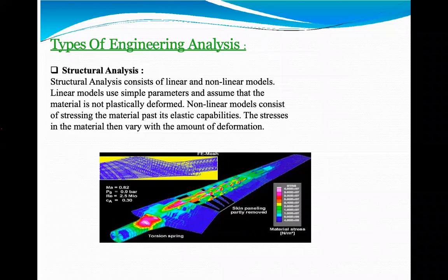Between the casing and the turbine blades we have a small clearance, and when the blades are revolving, if after a certain time they deform more, or the strains in those blades are more, then the clearance will get smaller and smaller, and at one time the blades may hit the casing, and that may cause a failure.